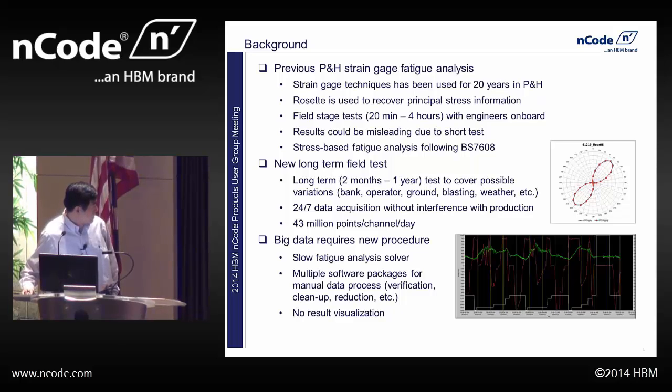The core of the fatigue analysis is a critical plane approach method. This picture shows a typical fatigue life calculation result from that method. It's a stress-based method, so it calculates the stress at different angles at one gauge location, then accumulates the damage there.